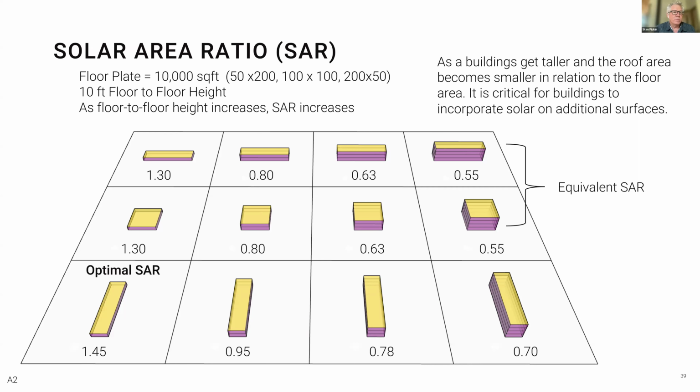One of the systems we looked at is just a set of louvers for shade management on the side of a building. And so it actually increases the surface area of a facade, but in a very interesting way, to help manage heat gain to an otherwise fully glazed facade. So I don't think it's a simple answer, and I think it's actually the point of departure for really interesting design solutions. So yeah, I think it's a great question.